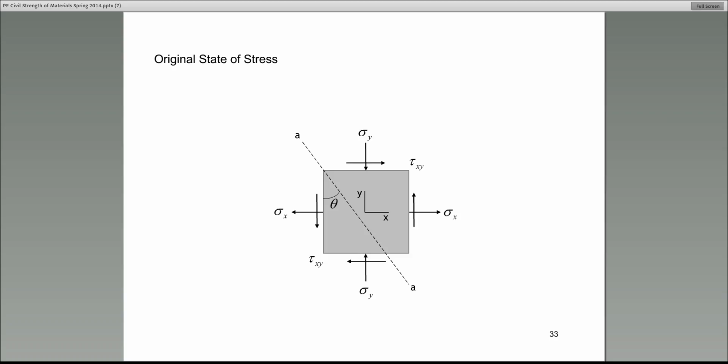In other words, what we have talked about so far, we looked at a beam that's subjected to bending. We calculate the bending stress. We looked at the shear stress in bending. And in the very, very beginning, I showed you an equation that told you how to calculate normal stress. Remember the comment I made about normal stress, sigma is equal to P over A? Well, we only looked at isolated stresses. In real situations, those of you who are structural engineers, you will agree with me.